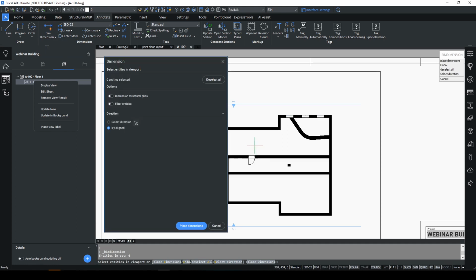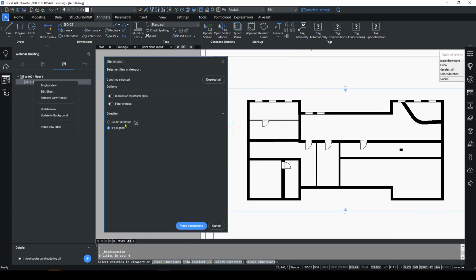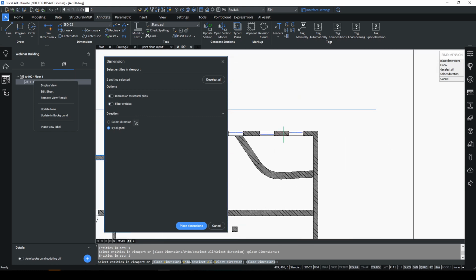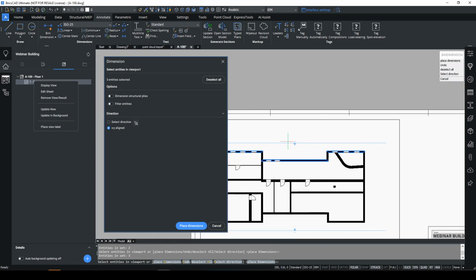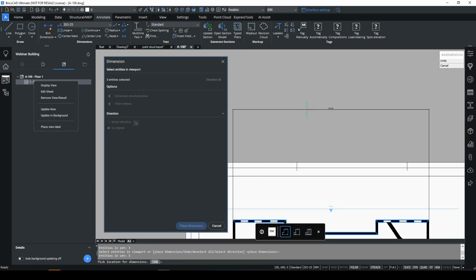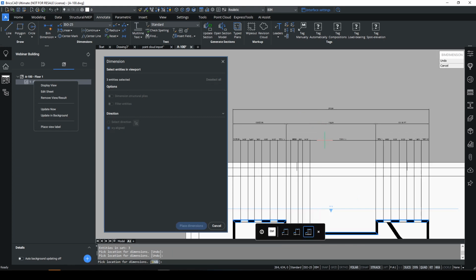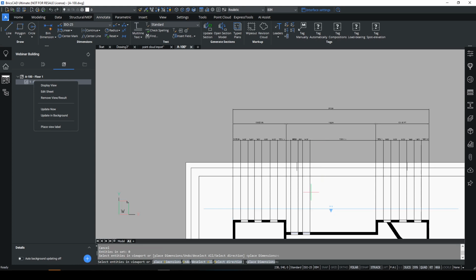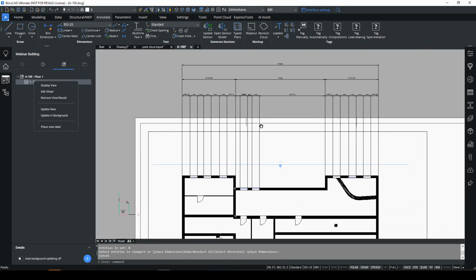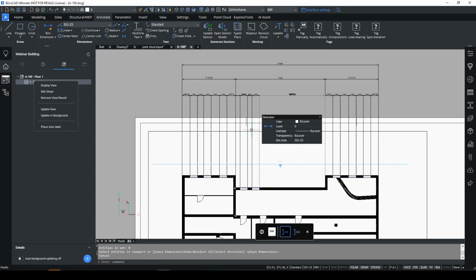So on the BIM dimension tab, you could get quite clever and use the filter options and select all the walls through the properties, but often it's quicker just to go and click these things manually. So I click on these walls here, I will press enter, and I'll put these dimensions off the sheet to make them very clear. If I press Control once, it will do the wall spans. Press Control twice, it will show all the individual dimensions going through the various windows. So we can very quickly run through the drawing and populate those.